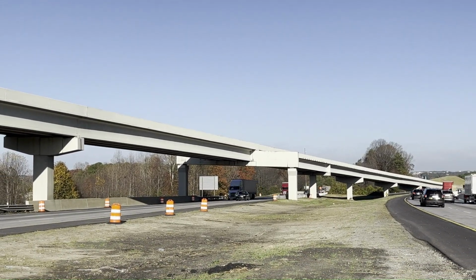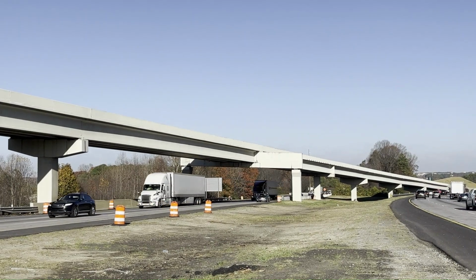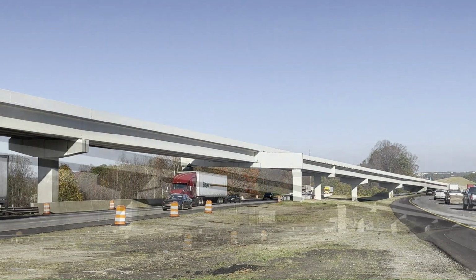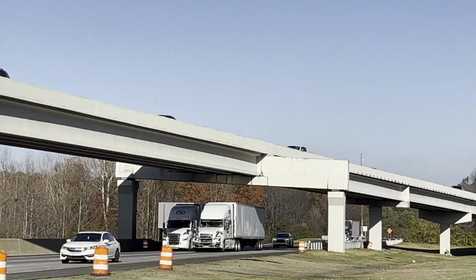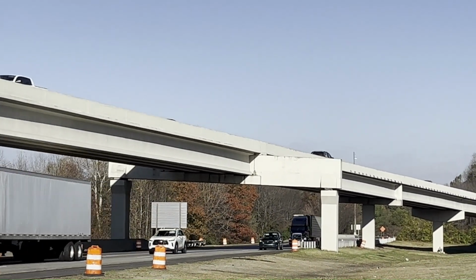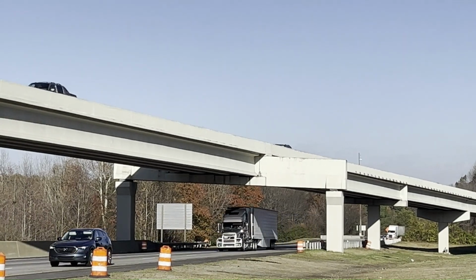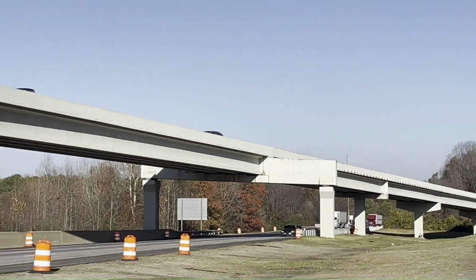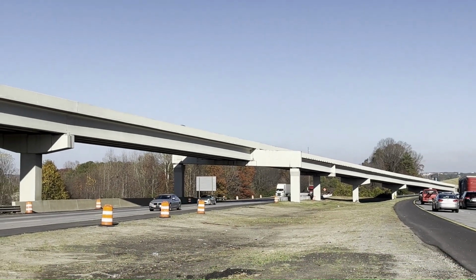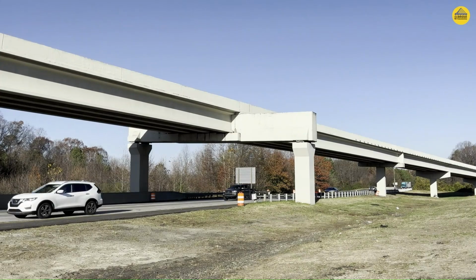Another option that could have been adopted is an eccentric location of the pier from the bottom carriageway, and in that case we would have a very large span of the cantilever pier cap, and that will be subjected to huge eccentric moments which will go all the way to the foundation as well. Hence, the portal becomes the best choice in such scenarios, and that is the reason why we are seeing a portal frame at this very location.